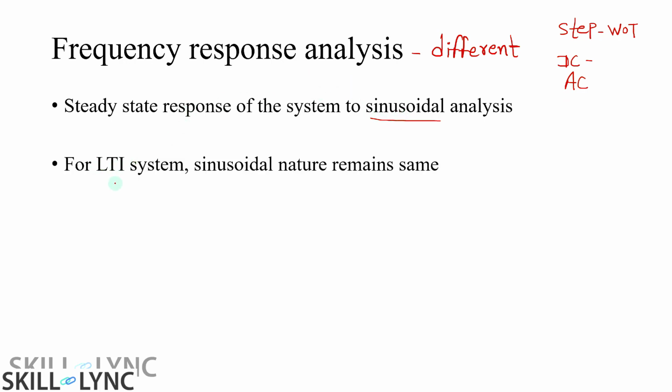So this frequency response analysis is based on the sinusoidal. For linear and time invariant systems, the sinusoidal nature remains the same. So if you give sine as input, you are going to get sine in the output. That is the nature of the LTI system, linear and time invariant system.